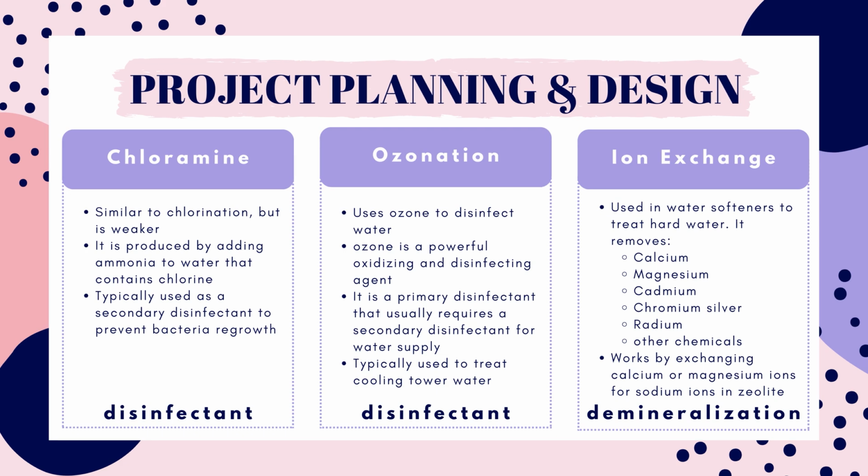Ozonation is a water disinfection method that uses ozone, a highly reactive form of oxygen, to treat water. This process not only disinfects water but also helps remove taste and odor issues and oxidizes various organic and inorganic substances. Ozonation is a chemical-free and environmentally friendly method for water purification.